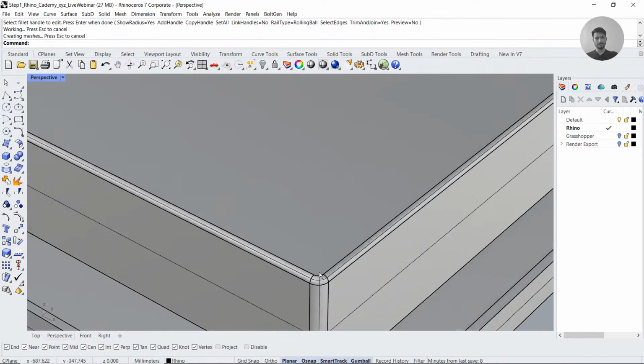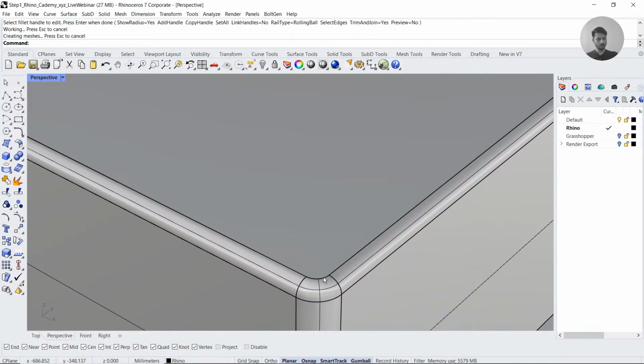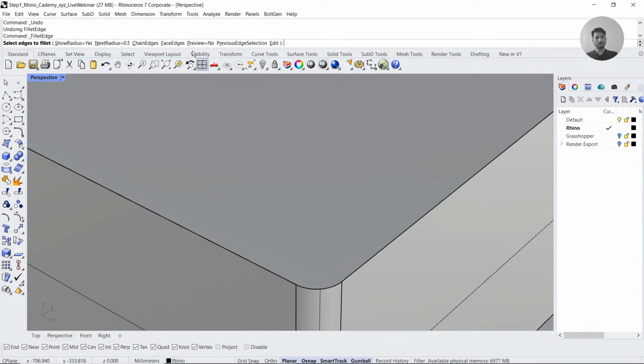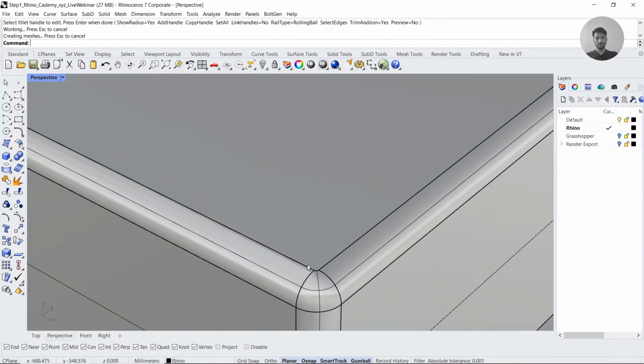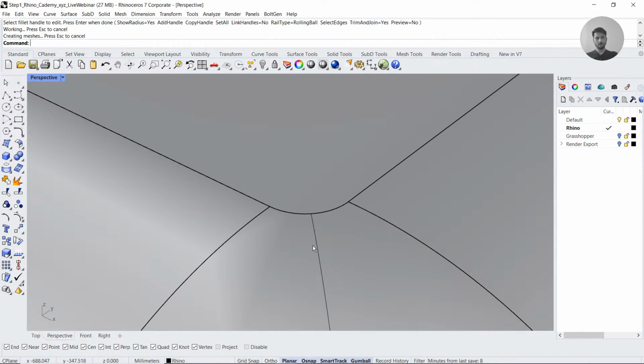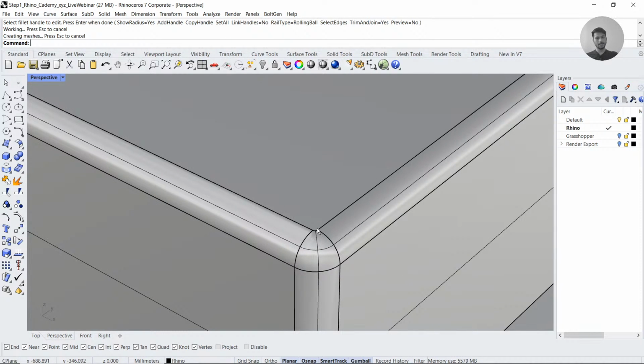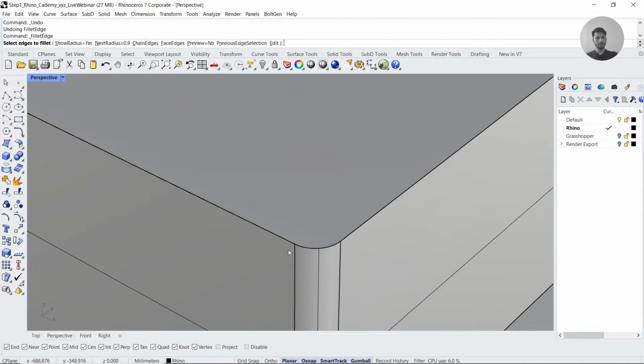So here you can see there is no issue. You can use any fillet amount that is lower than 1 and it should work. Even 0.9 should work. It's just that if you provide the same amount, it creates a point and it can give you an error. So in this case, it's just 0.5. We want a really sharp edge.